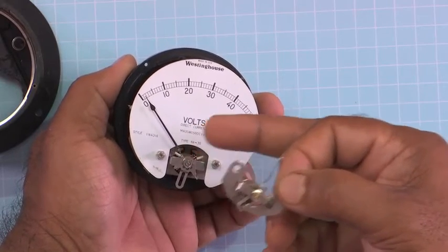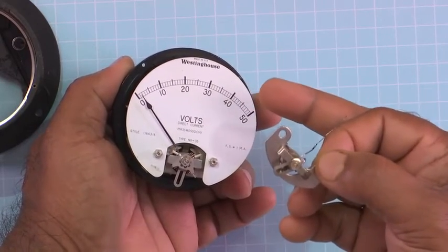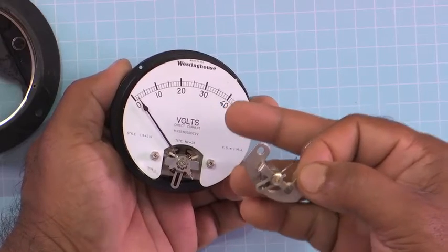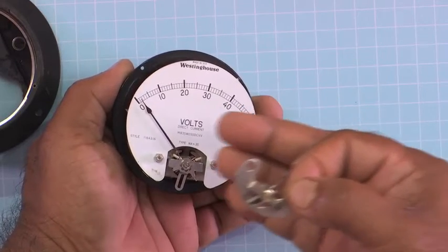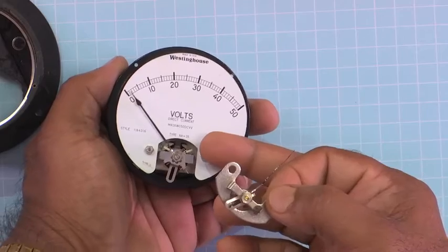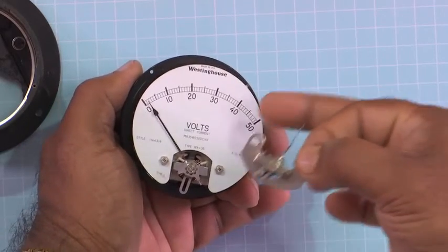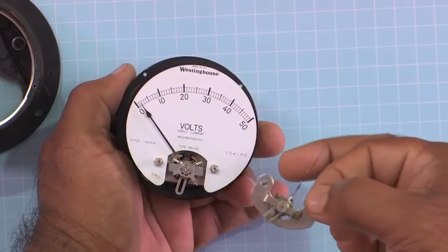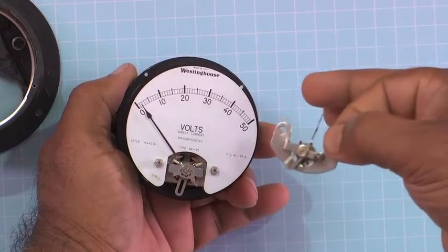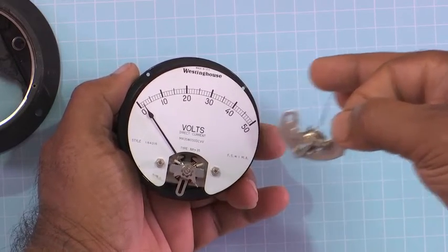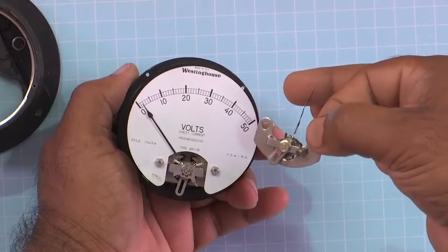In the case of an ammeter, the shunt resistance is connected in parallel to this galvanometer, and in the case of a voltmeter, a high resistance is connected in series with this galvanometer. This is the difference. That I will show you in calculation.